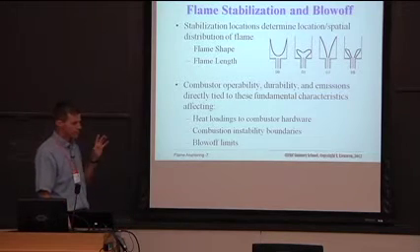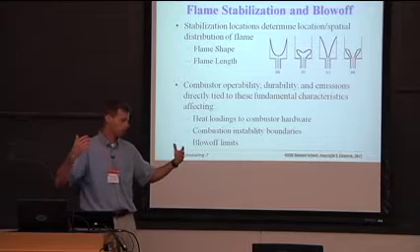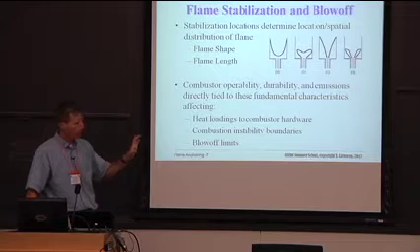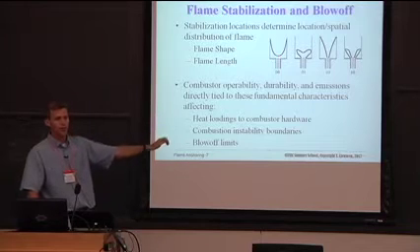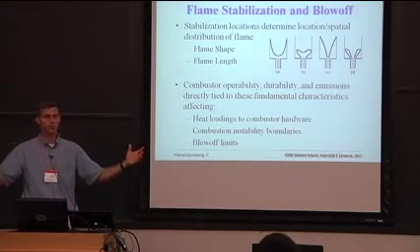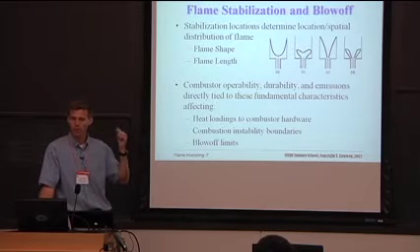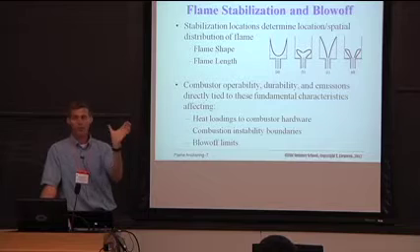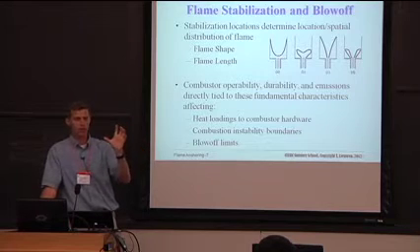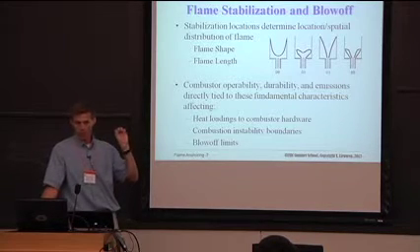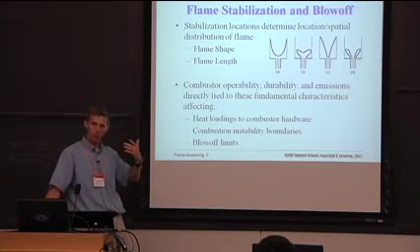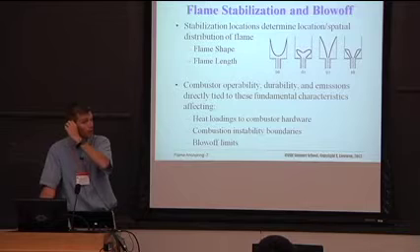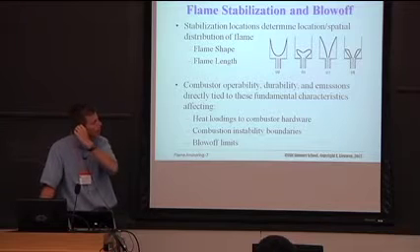The reason for that is that this was a great big 250 megawatt gas turbine. They'd be creeping up in power, and all of a sudden at 95% they would hit this enormous combustion instability. By the way, the example that I gave you in Chile about what happened was they would hit this enormous combustion instability, and their combustion chamber was actually lined with big ceramic tiles. And before they could pull the instability back out of it, one of those tiles would go flying downstream. You had a 10-pound hunk of ceramic in your turbine.